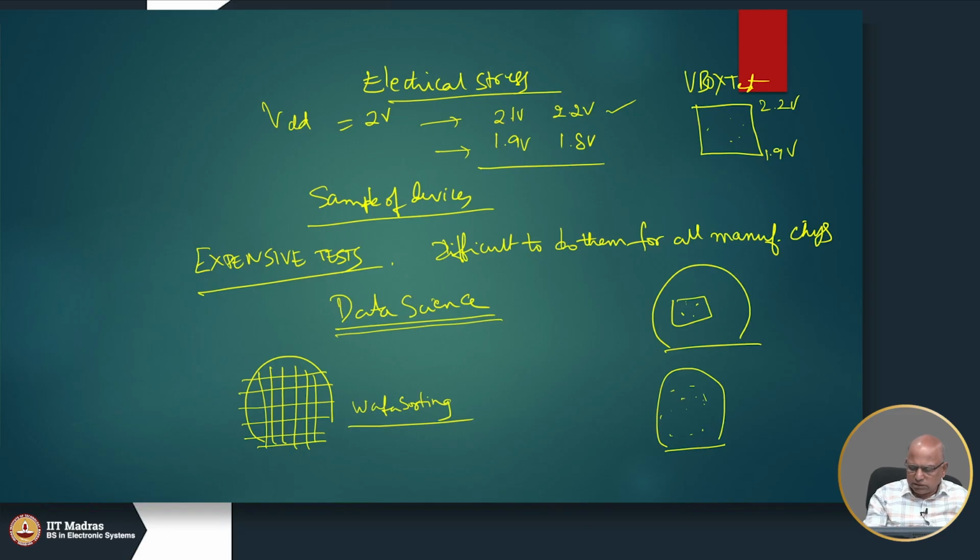What if the VDD itself is not connected correctly to the circuit? It is not going to function, it is dead. The clock may not be connected, ground is not connected. These are all really bad things that have happened, so it may be fairly easy to identify those in the wafer itself without having to package them.